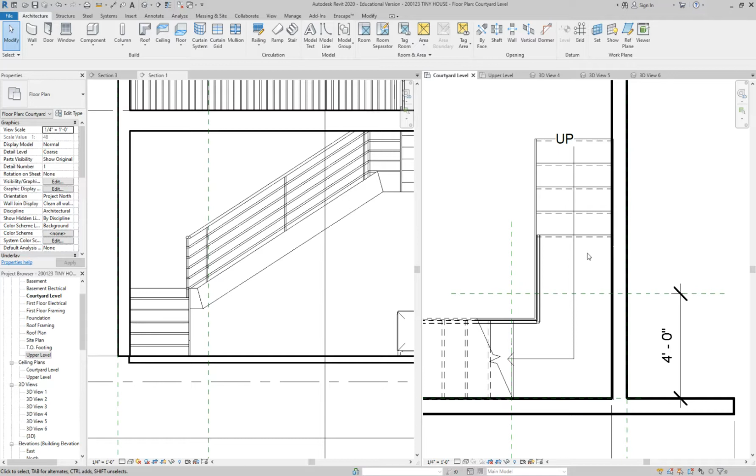And we can always edit that after the fact, because again, you guys saw, I'm not kidding, I don't know how stairs are gonna lay out. I can't automatically calculate that in my head or offset it like I would in Revit. This is such a more exact way of drawing stairs than just offsetting lines or drawing lines in hand drafting, okay? So now we have our landing. We don't know if it's right. We can come back and draw reference planes, or we could have had those reference planes there at the start. You could even use the move command to adjust where the different stair segments go, okay? You can do L's, you can do U's, there's many things that you can do.